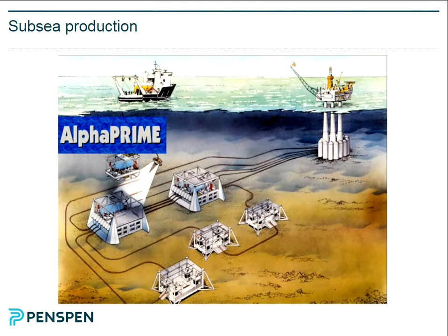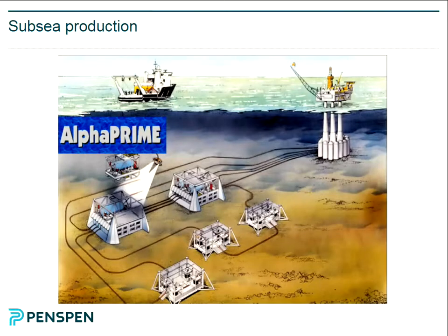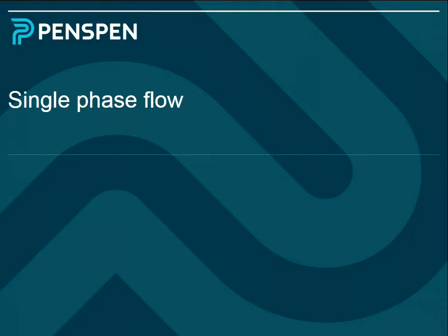And then you've got the elevation term, gravity by density by the difference in height. Very, very simple. The thing about this one is that for single phase flow you get it back again. So if you go up a hill, pressure reduces when you get to the top. When you come back down the other side, you get it back again. With multi-phase flow you don't get that. Multi-phase flow is not reversible. You lose energy going up, you don't get it back again, basically. So reversible with single phase flow.